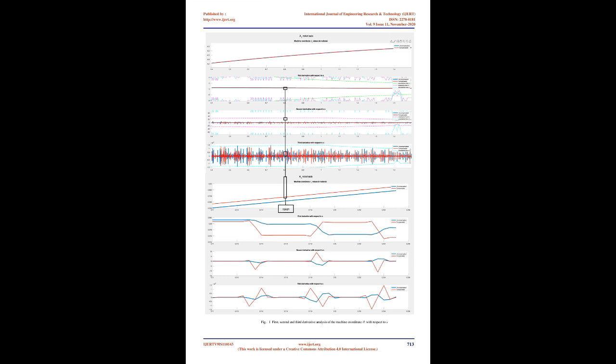The equation 20 actually determines the first derivative's constraints of the functions, raised out of velocity limitations. The first derivatives have to satisfy the constraints as well, raised out of the acceleration and jerk limitations. In total, there are three constraints for the first derivatives of the functions. In equations 22 and 23, the notations are the acceleration and jerk limitations for the ith axis respectively.